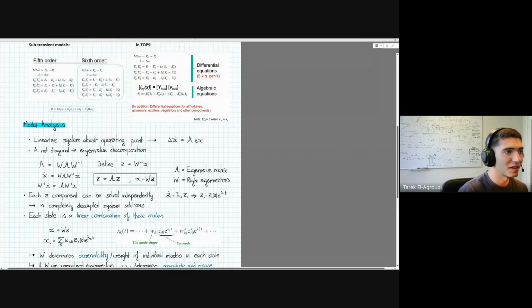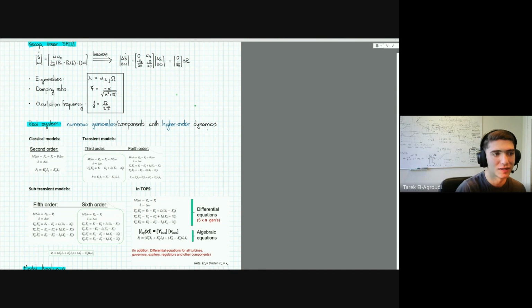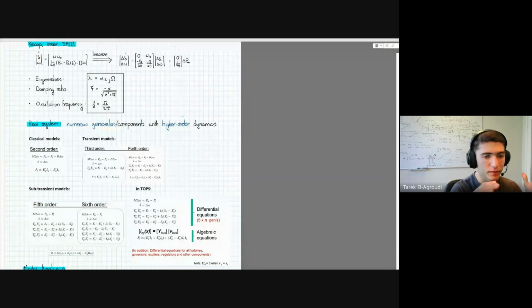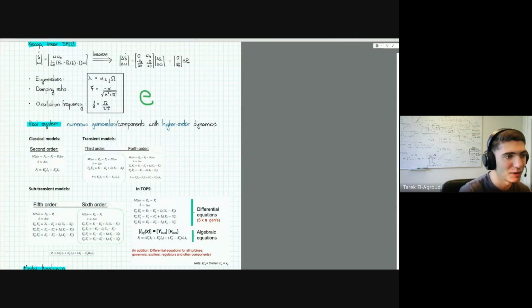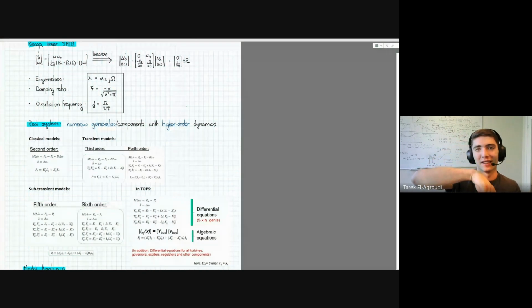It no longer looks at just the states separated in the generators, but it looks at the characteristic modes. If you have 90 states in your system, then there will be 90 specific eigenvalues. Because in linear analysis the response is just e to the minus lambda t, each eigenvalue of a system matrix corresponds to a specific amount of oscillations and damping.